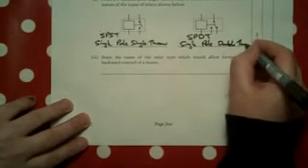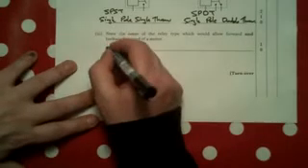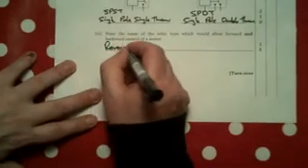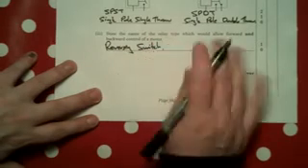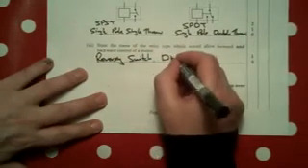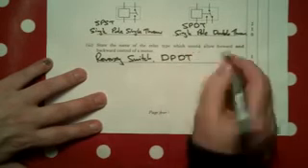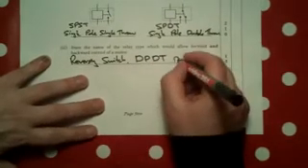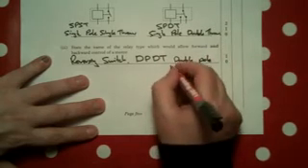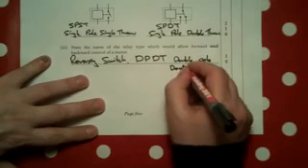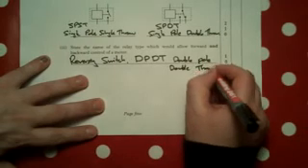State the name of the relay type which would allow forward and reverse motion. It's sometimes called the reversing switch, but we call it double pole double throw, DPDT, double pole double throw. That's that question.